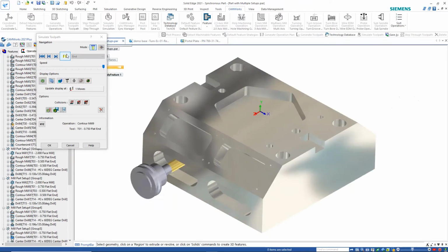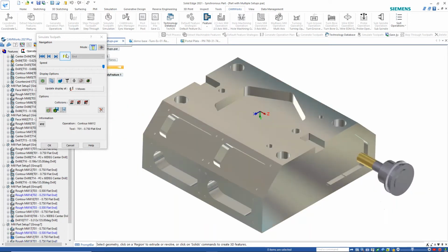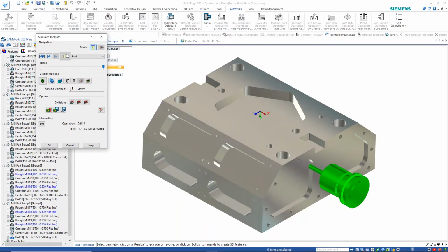So all this is done right here in Solid Edge, and you can see how integrated and embedded CamWorks for Solid Edge is, and also you can get an idea of the automation and how much that automation adds to allowing me to be able to create a CNC program very quickly inside Solid Edge. So in just a few minutes, I've created this program.